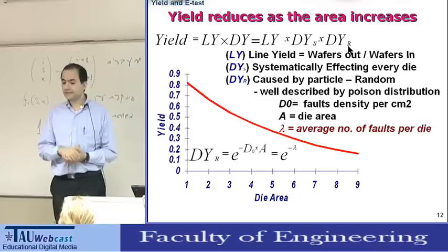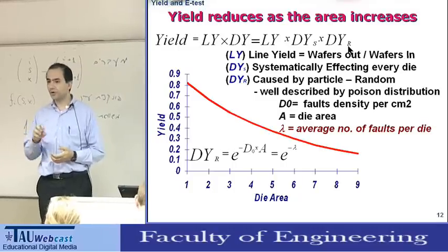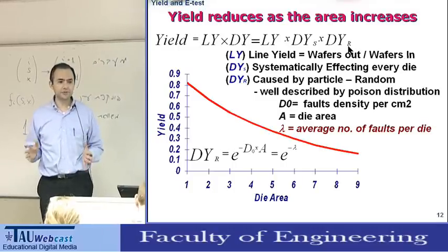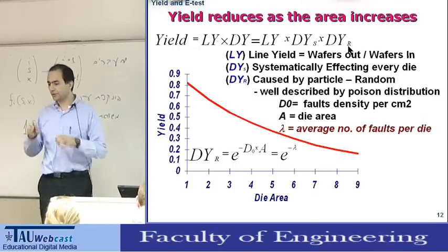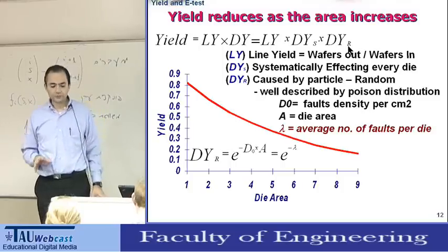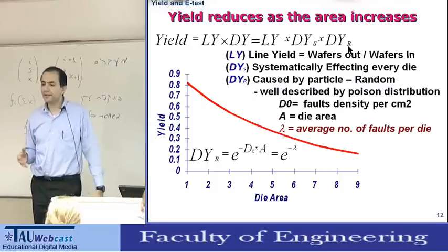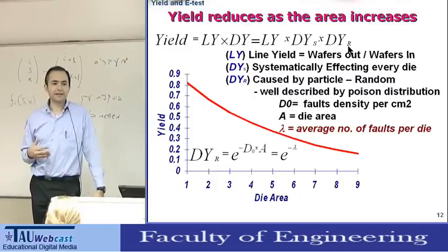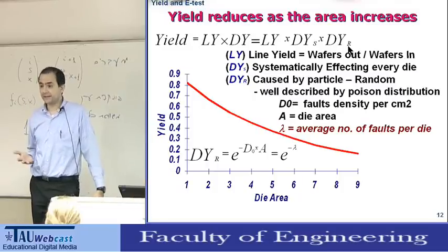So it's not just one contact which is not open, but there are many contacts which are not open, and they're not only on one die but on several dies on the wafer. So if we have a systematic problem, it could reduce the yield by several percents. Okay?